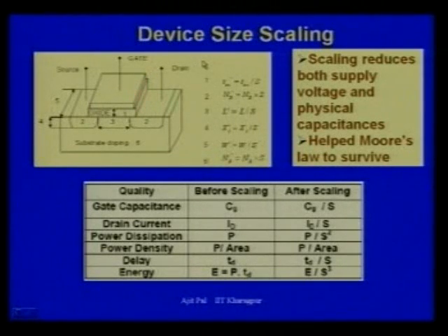In constant field scaling, you are reducing the various dimensions. As a consequence, capacitance is decreased, current is decreasing. Current is decreasing because you are reducing the supply voltage as well, which is not shown here. Supply voltage and threshold voltage are reduced by the same factor S. And your capacitance is reduced because length, width, thickness of the silicon dioxide are reduced, and as a consequence, gate capacitance is reduced because this is the MOS capacitance.